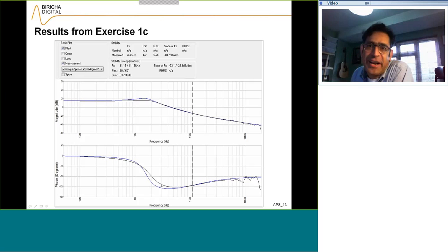And of course, the reason for that is that we have typed in the DCR value of the inductor, the DC resistance of the inductor, but of course, we are now dealing with the AC resistance of the inductor, which is higher. Therefore, you have a lower Q because you have more damping. And the effect of damping is that it reduces the height of the bump, and also it shallows out the phase degradation. So this is exactly what you expect to see.